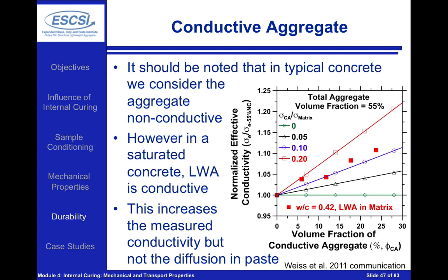This is because the aggregates themselves are going to conduct in the system, and you're not just measuring the paste properties. And if this is a question that arises, we'd be happy to help you do the calculations to figure out how to account for the conductive aggregates.